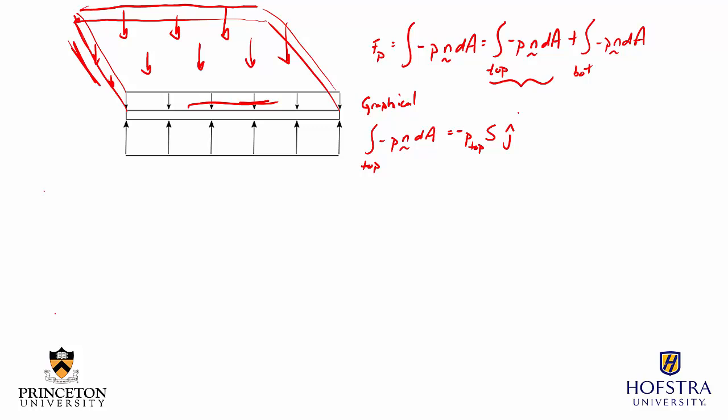If we wanted to do this with more thorough mathematics, looking at that integral, we can, and let's do that by creating a coordinate system. I'll create a y-axis and an x-axis, and we'll give some symbols to the overall length in the x direction, which I'm going to call c. The value of x at the end here is c, because typically we call the length of our airplane wing the chord. And the value at the tip for the length of our wing, I'm going to give the symbol b, because we typically use b for the wing span.